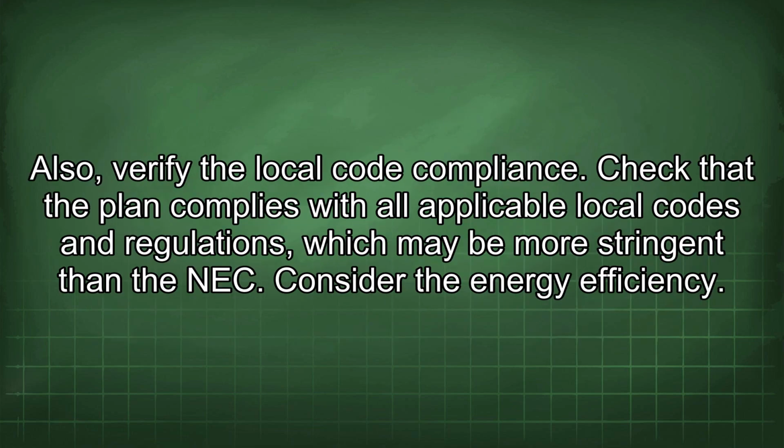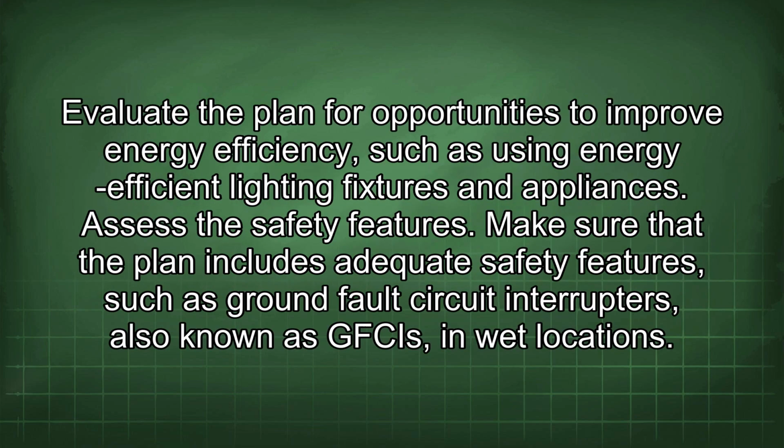Also, verify the local code compliance. Check that the plan complies with all applicable local codes and regulations, which may be more stringent than the NEC. Consider the energy efficiency. Evaluate the plan for opportunities to improve energy efficiency, such as using energy-efficient lighting fixtures and appliances. Assess the safety features.